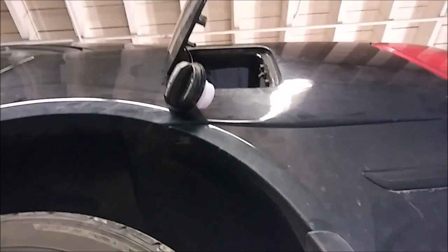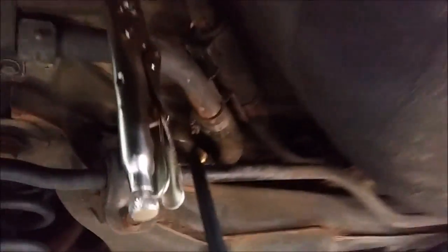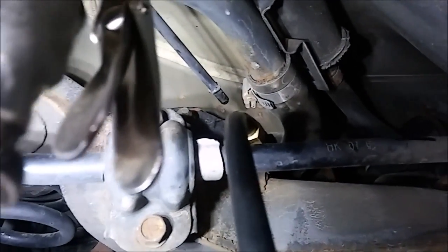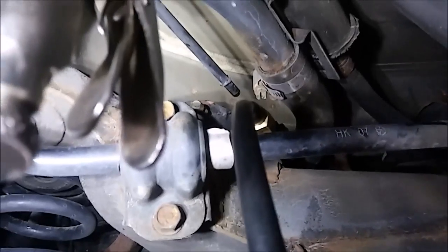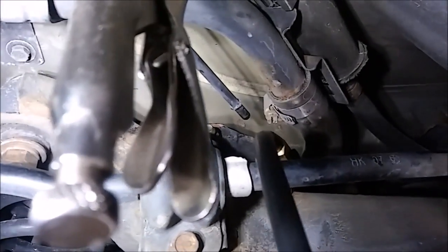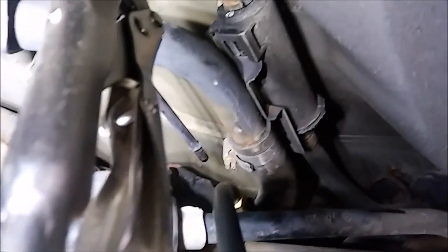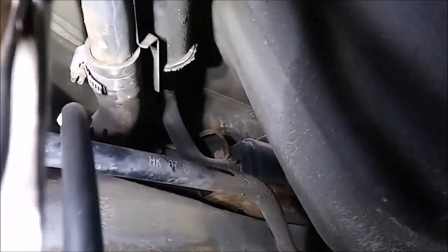I have the fuel tank off up there, just looking for smoke, and I can't get any smoke to that point. So there's obviously some sort of a check valve involved in whatever hose I'm connected to, but ultimately what it means is that this test location is not going to work. Oh man, this generally isn't this hard on most cars, guys. We're super limited by access to this canister.